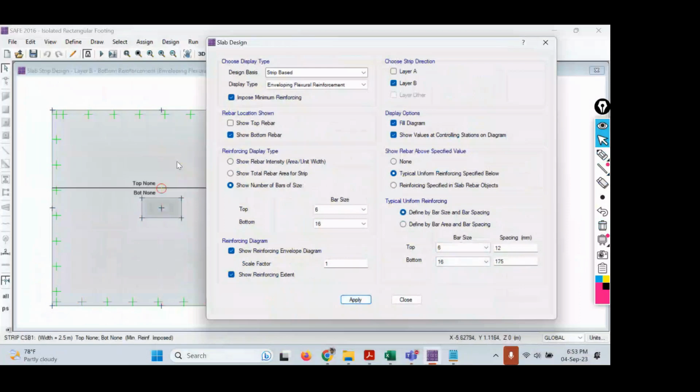You can see there is no moment. That means perfectly it is fine, so there won't be any problem with the footing. If you change it to 100, again you will not see. Let us change it to 300 as the spacing. Probably now you will see. Right? Can you see? So you have to decrease the spacing in order to restrict the moment.